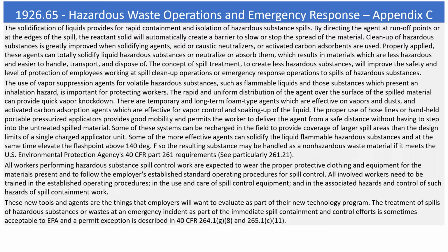Some of these systems can be recharged in the field to provide coverage of larger spill areas than the design limits of a single charged applicator unit. Some of the more effective agents can solidify the liquid flammable hazardous substances and at the same time elevate the flashpoint above 140 degrees Fahrenheit, so the resulting substance may be handled as a non-hazardous waste material if it meets the U.S. Environmental Protection Agency's 40 CFR Part 261 requirements, see particularly 261.21.